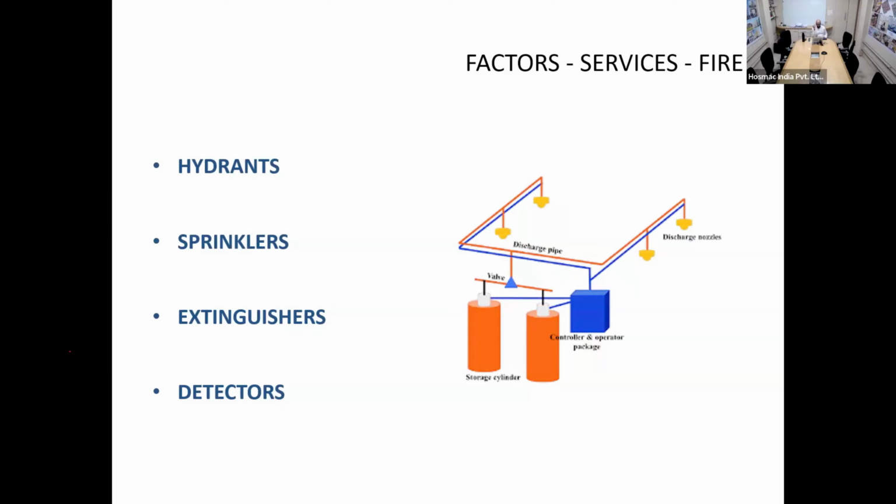We have something called a gas-based suppression system, which is an inert gas, which is not too heavy because it should not asphyxiate the patient, but will be heavy enough to quell the fire. So that's something that you need to insist upon in areas where you cannot use conventional sprinklers. The network of piping is similar to what you use for sprinklers, but instead of water, you have a certain proprietary gas which will quell the fire, without exposing the patient to any kind of particulate matter.